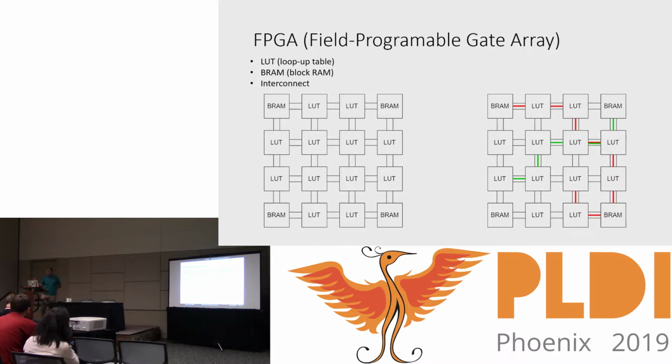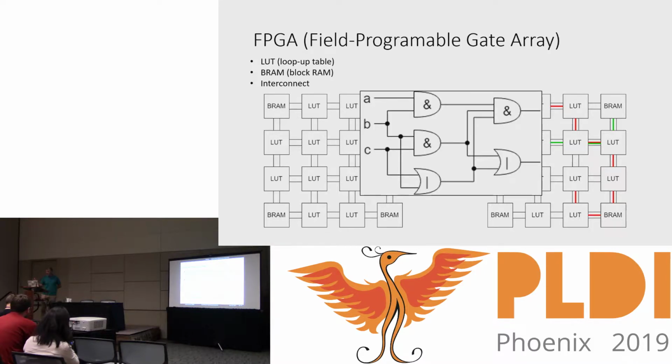I also included these blocks, these tiles labeled DRAM, which just stands for the memory that is stored on the FPGA fabric itself. So it's not directly accessible to the CPU as normal RAM would be. As an example, if we have a logic diagram composed of gates, the compiler can identify some clusters of these operations, of these functions, and wrap them together into individual lookup tables.